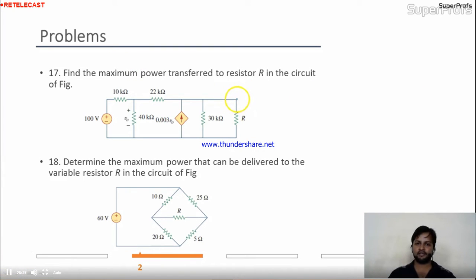To calculate the Thevenin equivalent voltage, we have to open the load element from the circuit. So here the voltage is VTH. This is nothing but the voltage across this point. These two are the same. Here I have the voltage V0, and over here I have V0. So can I apply nodal analysis here?